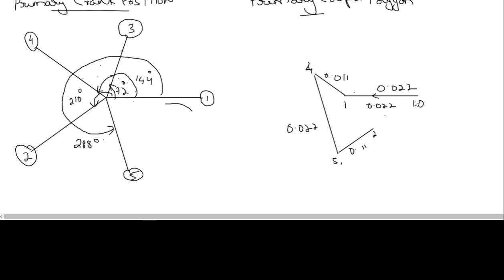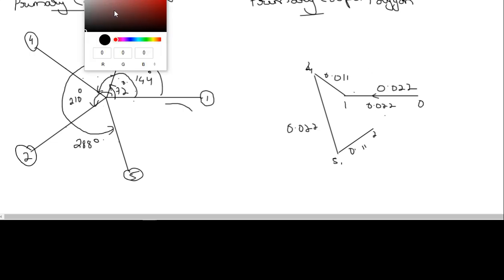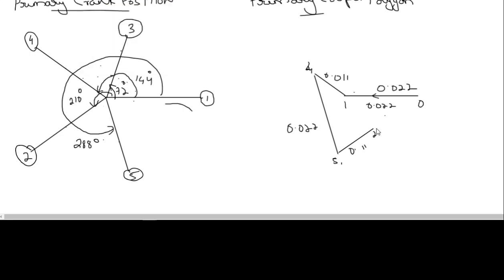And this polygon is not closing, that means there is an unbalanced force there. Since this polygon is not closing after 1, 5, 4, 3, 2, 1 firing order, that means there is an unbalanced force acting, which is of the length from here to here. And if you do it properly, you will get that unbalanced couple as length as,